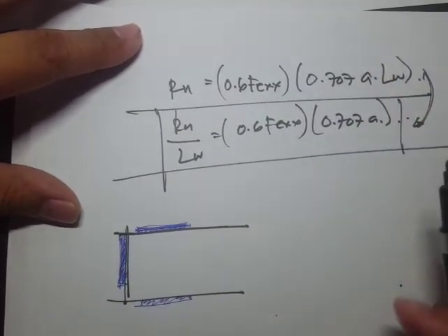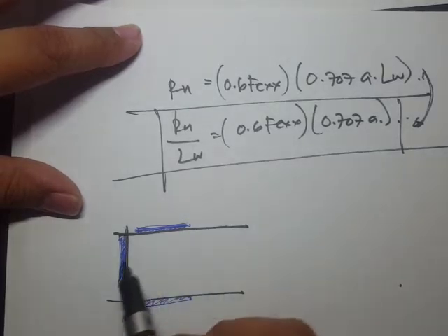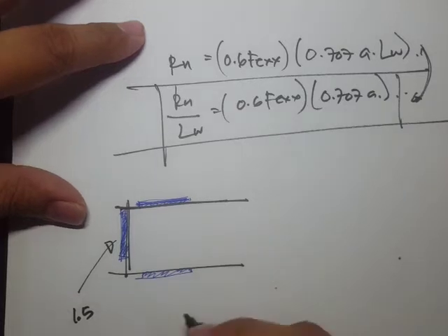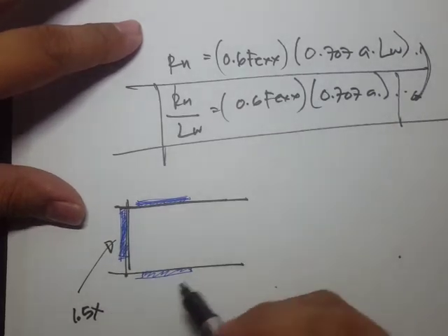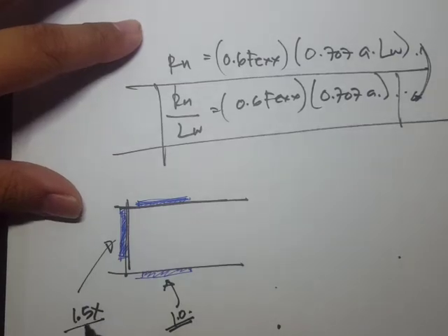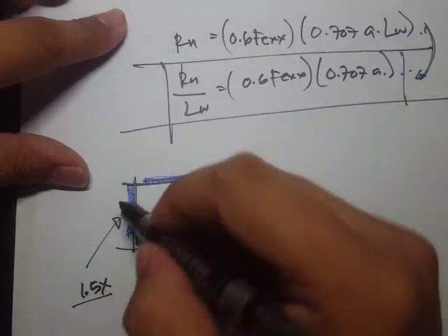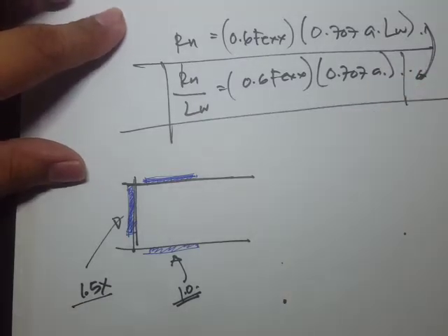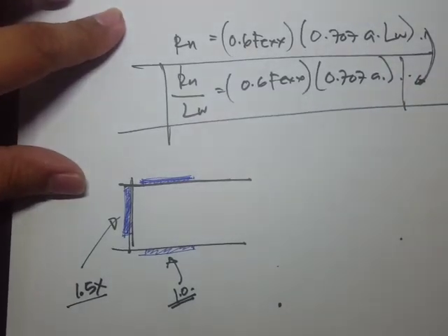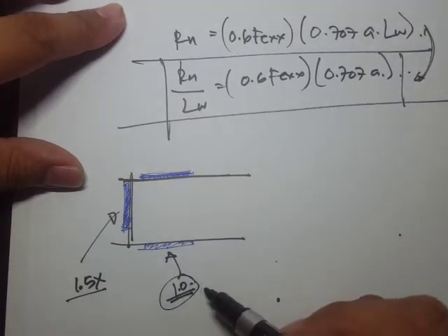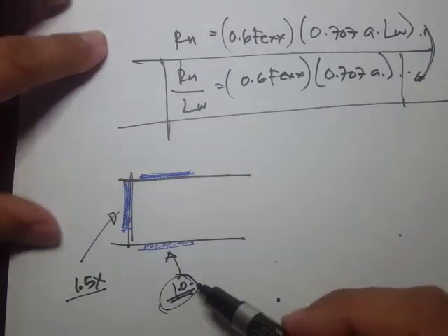However, for simplicity, there's actually an equation, and that's 1.5 times, but here let's say this is just 1.0, meaning you have a 1.5 times greater strength for this transverse weld. But for simplicity and in many reference texts, the computation is based on this.